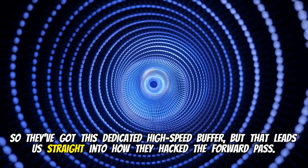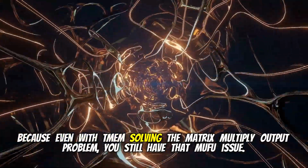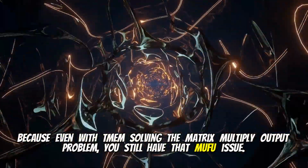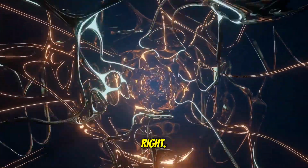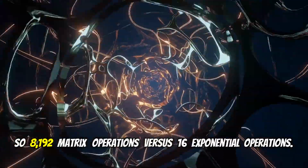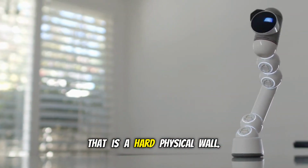So they've got this dedicated high-speed buffer. But that leads us straight into how they hacked the forward pass. Because even with TMEM solving the matrix multiply output problem, you still have that MUFU issue. The unit computing the exponentials for the Softmax is still physically stuck at 16 operations per clock. Right. TMEM doesn't fix the math unit disparity. So 8,192 matrix operations versus 16 exponential operations. That is a hard physical wall.